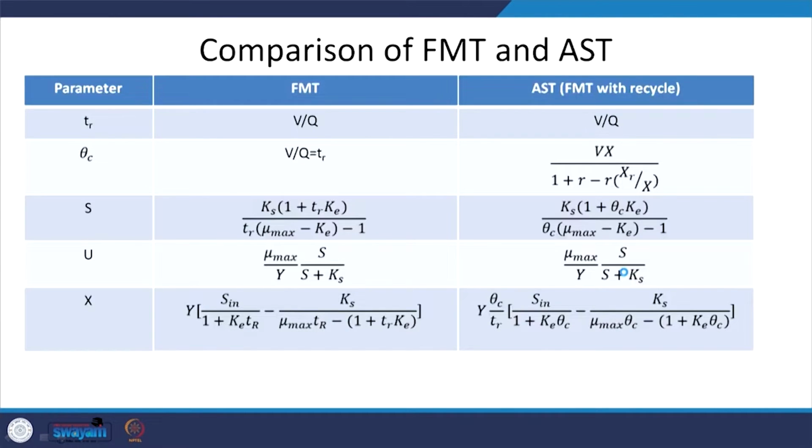And then we looked at this particular schematic table, where we compared a fully mixed tank without recycle and fully mixed tank with recycle. So, major aspect is that typically I use theta, sometimes people use retention time TR, to represent hydraulic retention time, but I look at theta. V by Q is the same for both. Theta C for the case where there is no recycle is going to be the same as theta. The solids are going to spend the same time as the time spent by the water molecule. That is what this indicates, where there is no recycle.